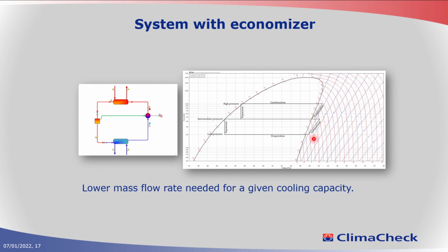It also cools down the compressor because the compression is done in 2 stages. So as you can see here, you have the first stage here. This is done internally in the compressor. So you come here on the suction line into the compressor. It compresses up to this intermediate pressure.